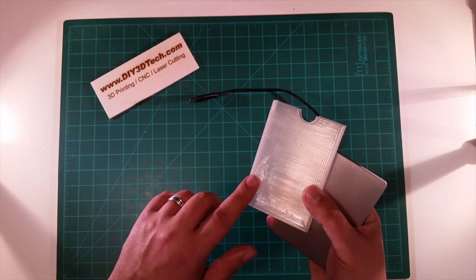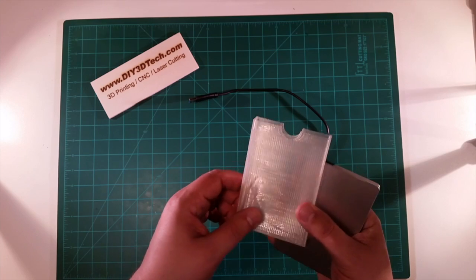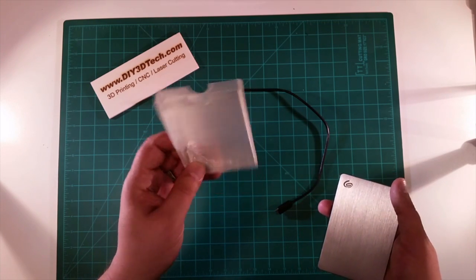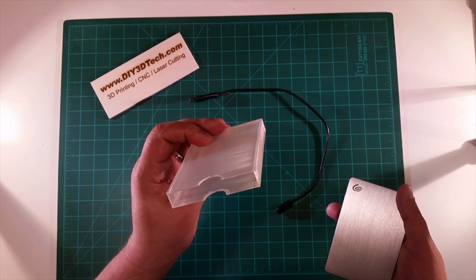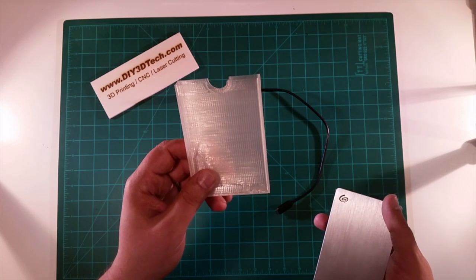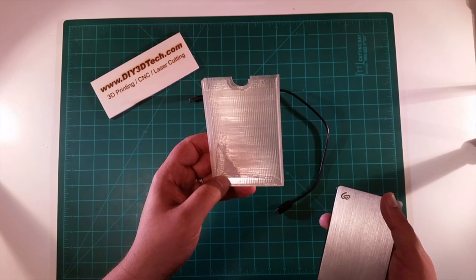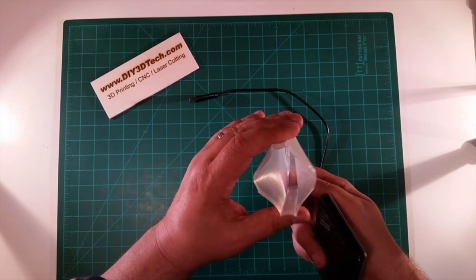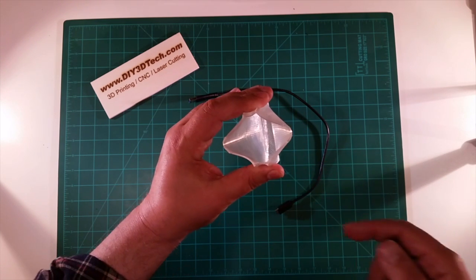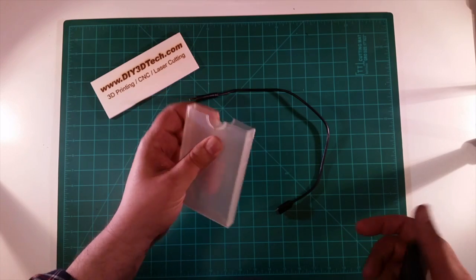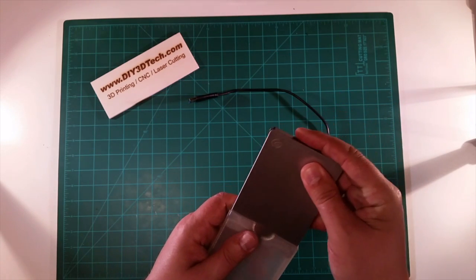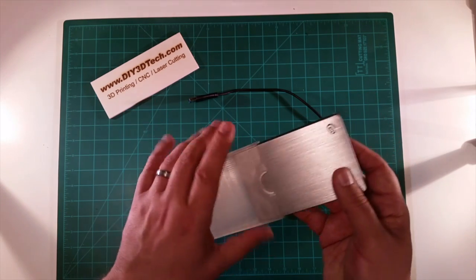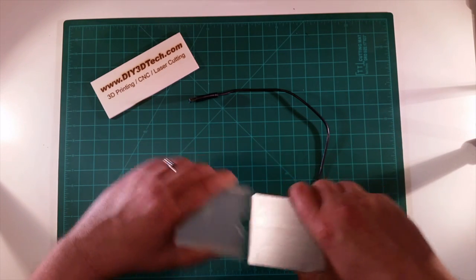And I think part of the problem is the temperature at which I printed this, because I have been printing TPU on the Wanhao at about 250 C, and I did it on the DaVinci, and the DaVinci does a nice job at it, but I think I'm running it a little bit too hot, and it extruded improperly, because one of the problems, I don't know if you can see in there, but it's kind of globbed in there. But again, the model seems to work very well, and this slides in, and I can slide it in until I get to this globular down here, and that's sort of the problem. So I'm not going to force it all the way in down there.